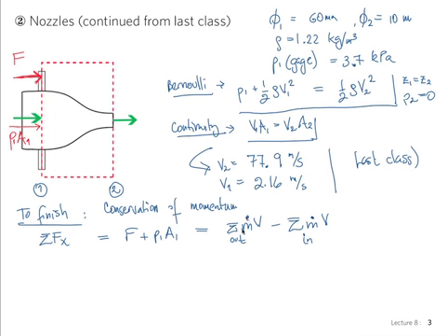In this case, we have all velocities perpendicular to our control volume, and we assume uniform velocity, like Nathan just said, and therefore the integral across control surfaces simplifies quite a lot, and we just have sum of momentum out minus sum of momentum in. The signs come about because the sign comes from the dot product between the velocity and the normal vector.